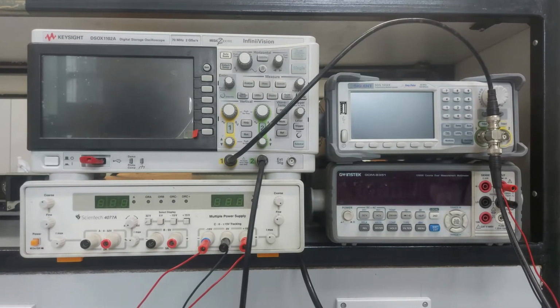And one more thing I want to tell you, that is the slew rate. So what is the slew rate? One more parameter is also defined. You are applying the signal at the input, and it will have some frequency. I mean, the input is changing with time, but the op-amp should be capable of responding to that change and giving it at the output. So there should be no delay between the input changing and the output changing.